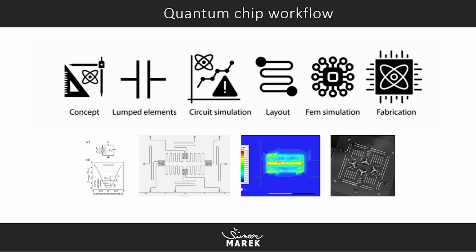Then we need to do a post layout FEM simulation, where we verify our design. And the next step is preparation for fabrication, or GDS generation and inspection of these files. So this is our quantum chip workflow.